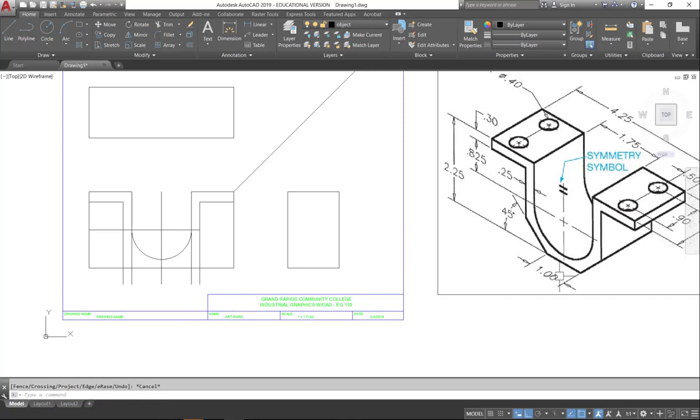So I'm looking at the bottom, and that's 1 inch. So it's centered because of my symmetry lines that I have here. So I'm going to offset that 0.5 each direction, 0.5, 0.5. I'm going to trim, using that as my cutting edge. I'm going to bring that guy up, that guy up. I'm going to have a line that's going to come from the intersection here. Turn my ortho off. Tab, 45 degrees.